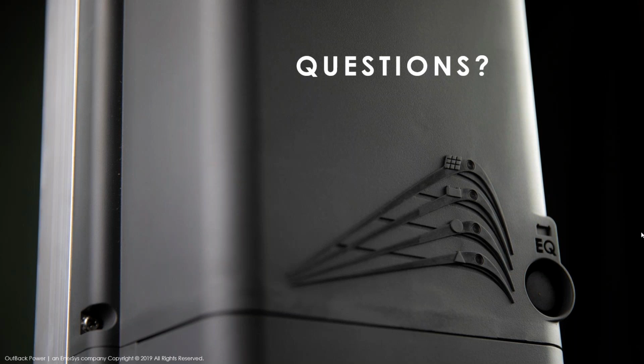So the FM80 would allow more energy than specified through its conversion system, and it would exceed the rating on the breaker. So the breaker would nuisance trip. That means there would be more current than expected or specified coming out of the FM80. And it would trip the breaker anytime that happened, which was bad user experience. So we reduced the maximum array size allowed on an FM80 to avoid that. So we've told customers for a few years now that array should actually be smaller than in the past to avoid that nuisance tripping.